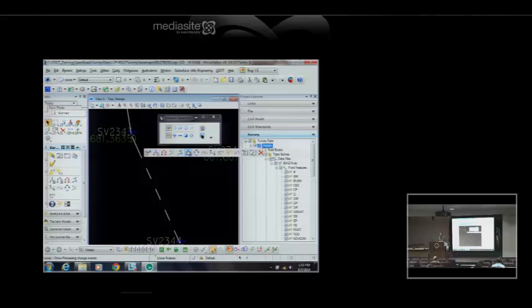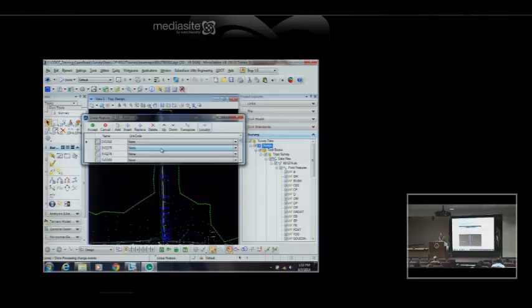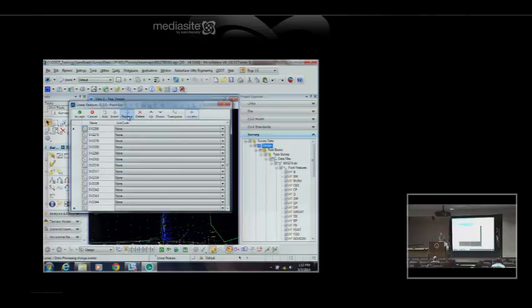But I can look at that point list here, manage the point list. So there's all the points that made up that chain. And if I wanted to delete one out or insert one, those functions are here to do that type of stuff. I don't know if that fully answers your question, but that at least gets you exposed to some of the editing tools. Does that kind of get what you wanted?